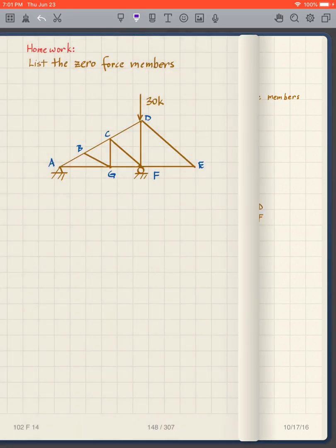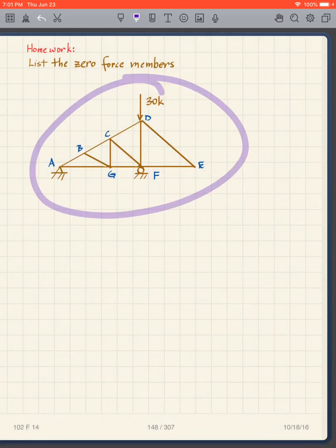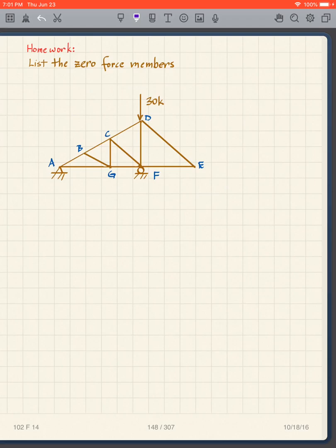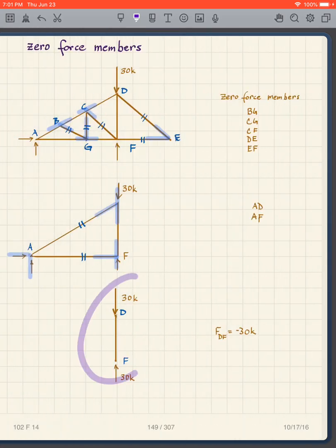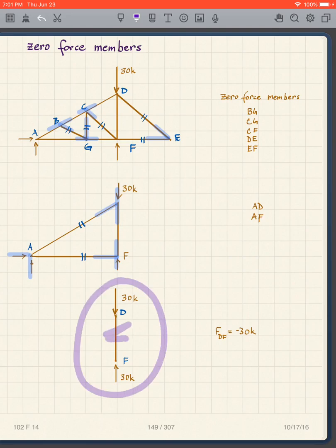So we'll go back to this whole thing. The only thing that's doing anything is that. Now, of course, in the real truss, we would never get rid of all this and just leave this one, because that's clearly not stable. But in essence, it does show that for this truss, with everything being perfect and lining up, the only member that is loaded is this member right there.